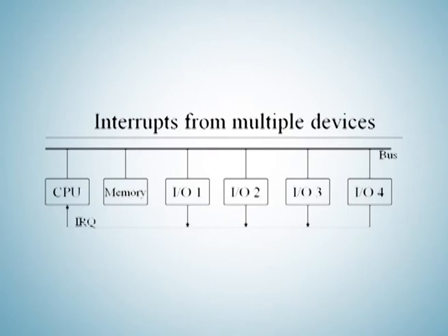The next design issue is how to handle multiple interrupts. When there are n I/O modules connected to n interrupts provided on the CPU chip, the process of identifying the requesting I/O module is simple and straightforward. However, when there are many I/O modules connected over the limited interrupt pins, techniques are needed to identify the requesting I/O module. There are several techniques to identify the requesting I/O module. These techniques also provide a way of assigning priorities when more than one device is requesting interrupt service.